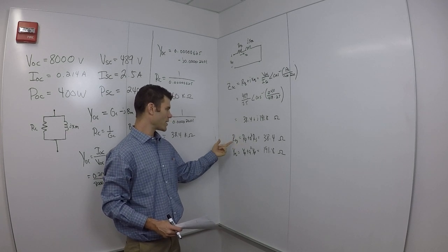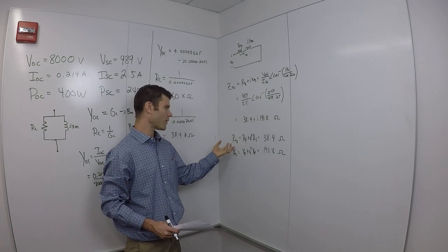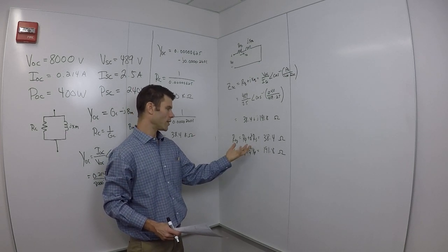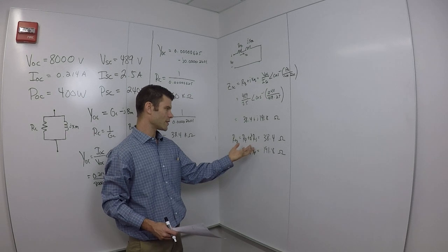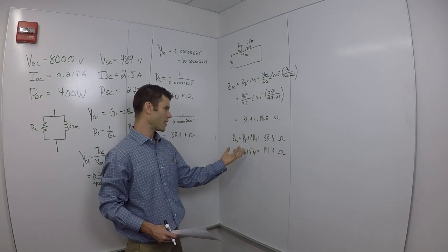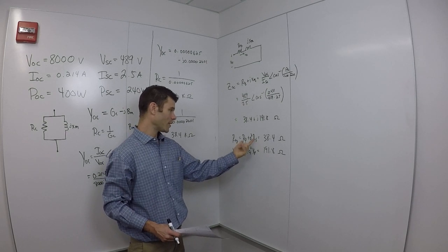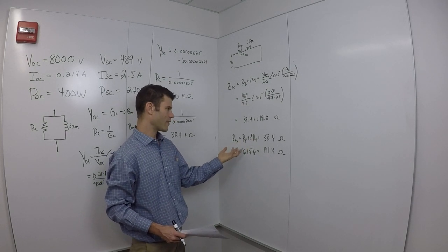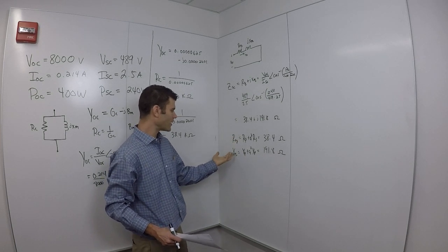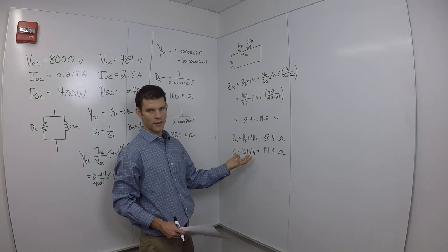But there are certain ways that we could find this. If we wanted to find this, we could make some assumption that says the secondary resistance is roughly equal to the primary. So you could say then RP and RS are exactly the same. Maybe they have the same windings. There's some way you can find out the ratio of the two. And you can find out the ratio of the primary leakage and the secondary leakage.